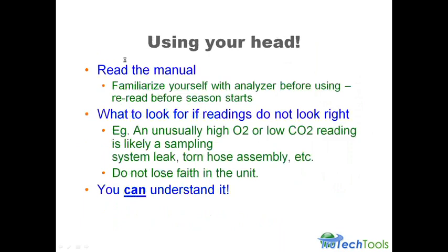And then use your head. Read the manual. Familiarize yourself with it. If you get unusually high O2 or low CO2 readings, it's likely a sampling system leak. But don't lose faith in the unit. They're real easy to understand.